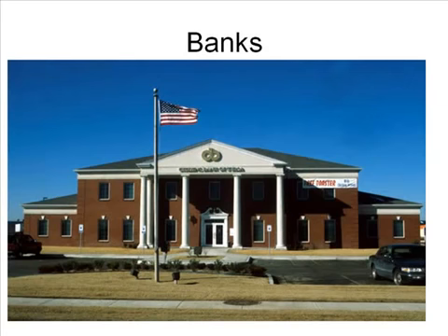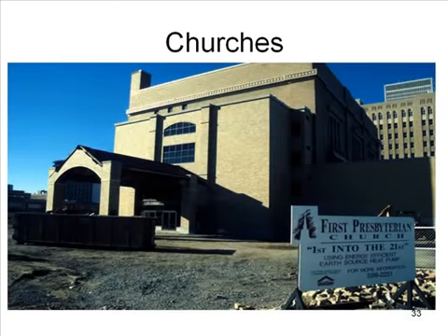We mentioned banks here, not because a bank is so unusual, but because its load is different. Now remember, all you need to know is the annual energy flows that need to go to and from that ground heat exchanger, and banks are different than schools and different than churches in this particular slide here. So how you handle that is by doing an energy analysis, and you pick off these loads by month, and having picked off these loads by month, then you can put them in these software programs and you can get a good design. I'm not so uptight about which program you use. I just want you to use one of them. Make sure that you use the science, and you can save yourself a lot of money, embarrassment, and maybe some lawsuits if you don't get it right.